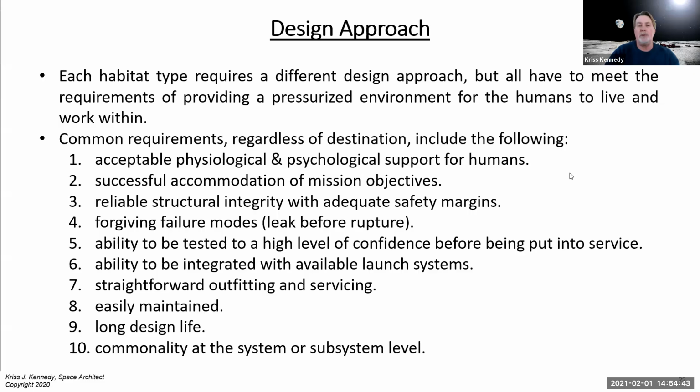Successful accommodation of the mission and science objectives, reliable structural integrity with adequate safety margins, forgiving failure modes, in other words leak before rupture, ability to be tested at a high level of confidence before being put into service, the ability to be integrated with available launch systems, straightforward outfitting and servicing, easily maintained and serviced, long design life, and commonality at the system and subsystem level.